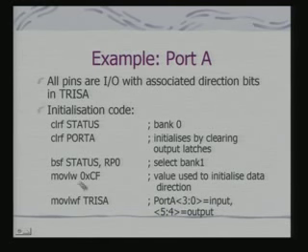So, this can be done by writing onto TRISA, and I am doing this by selecting the appropriate port address along with the appropriate memory bank. So, this is a typical code to be used for initialization of a port.